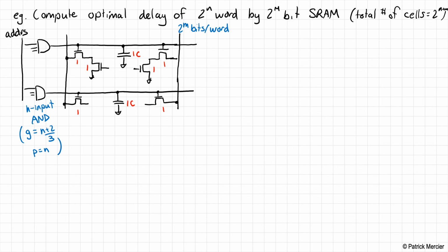The AND gate then activates an SRAM cell, which turns on and one side of the SRAM cell is going to discharge the bit line. Okay, so how do we go ahead and optimize this? Well, we need to generate H, B, F, G, etc. We need to do a little bit of alphabet soup in logical effort. But before we do that, let's just summarize a few things about this circuit.